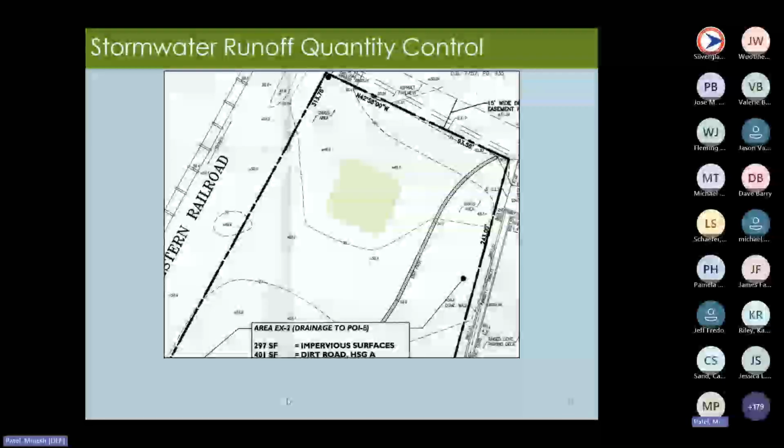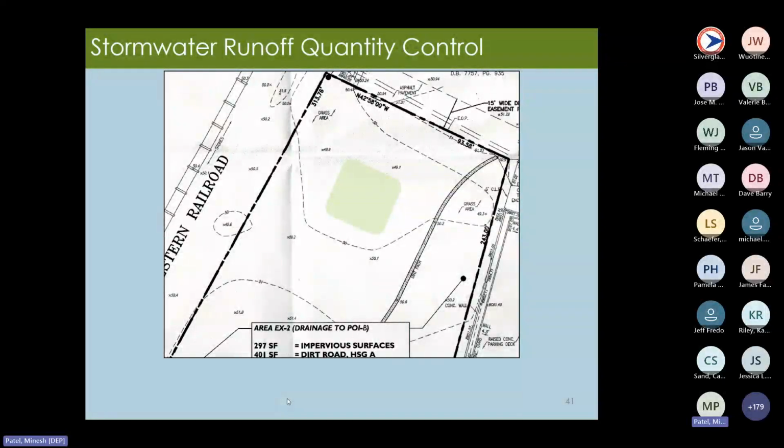On that same example site that was shown a couple slides ago, there was a 6-inch deep ponded area within the shape that's depicted here. This was ignored, and the basin was made significantly larger than was needed. If there are any questions as to whether areas of ponding exist on site and it cannot be determined from the photos of the site, you may have to just go there in person and see the actual site for yourself.